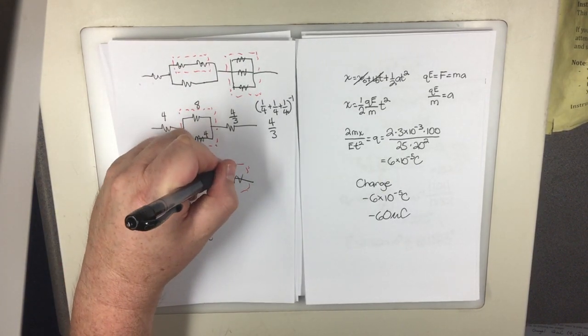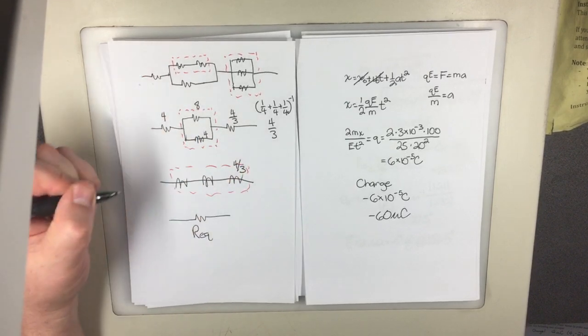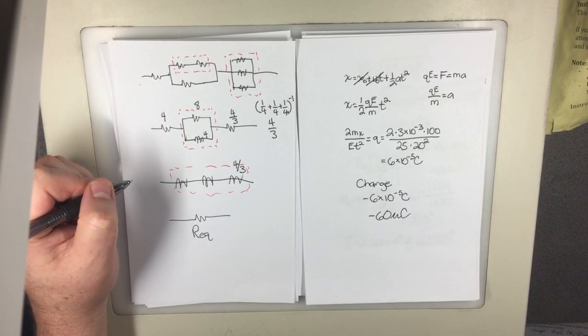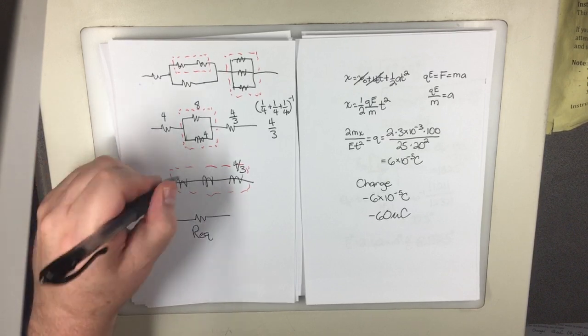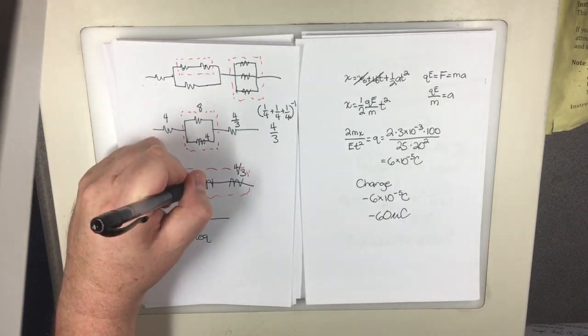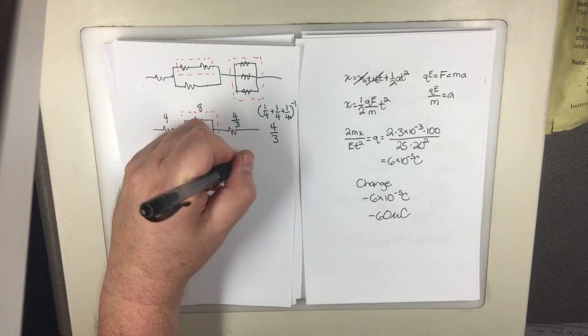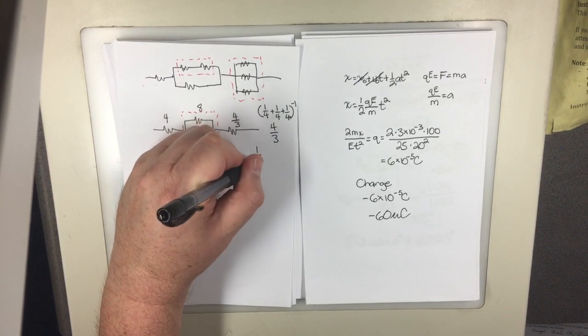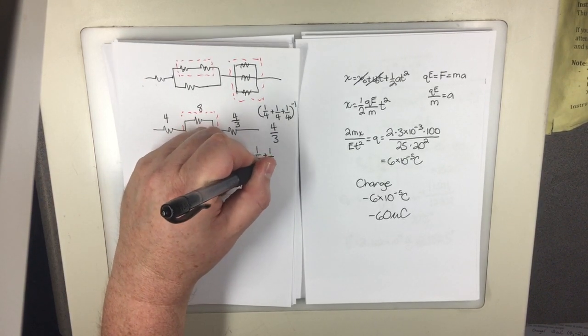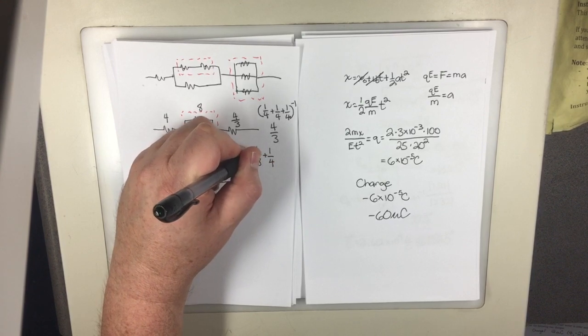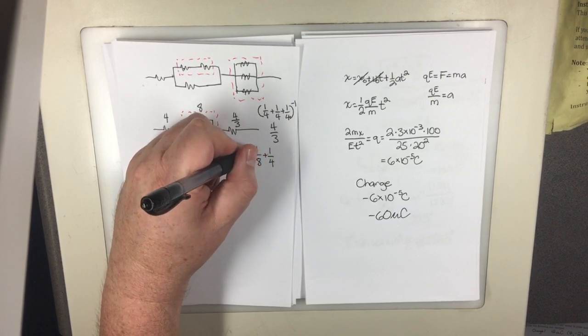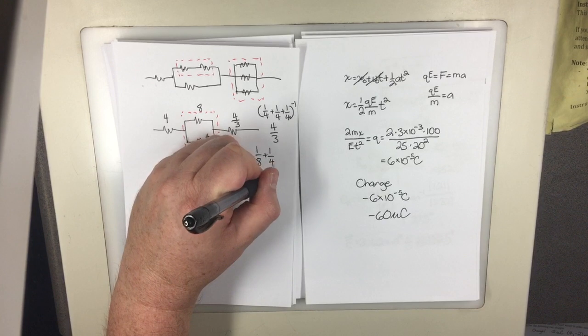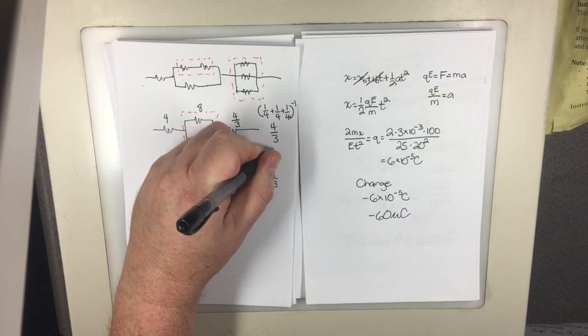That comes down, that doesn't do any changing. Remember, I'm using fractions. Do not use decimal until you give final answers. 4 becomes 4. And then this resistor, 1 over 8 plus 1 over 4. This is 1/8 plus 2/8, or 3/8, or 8/3.